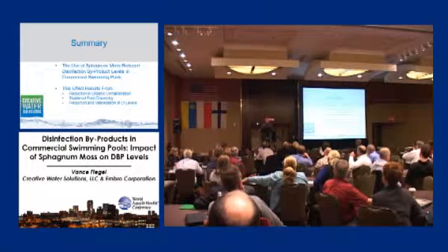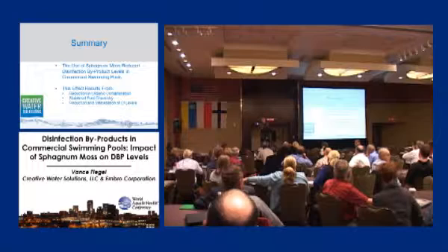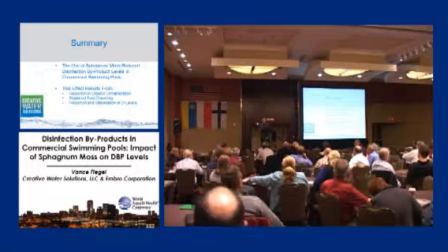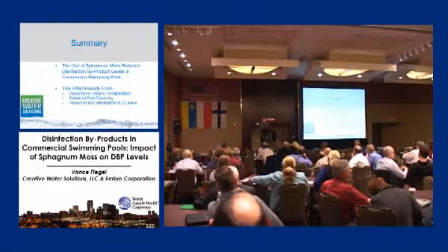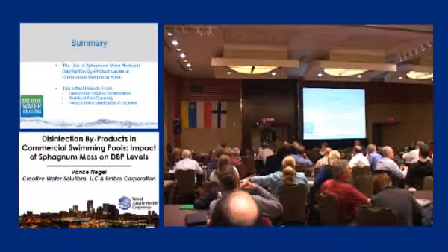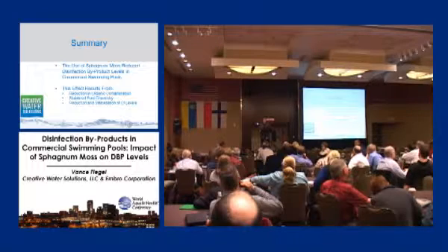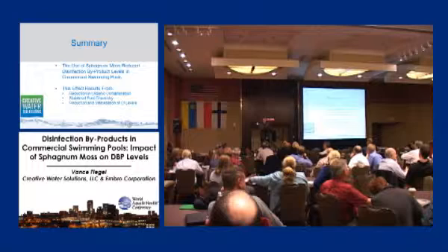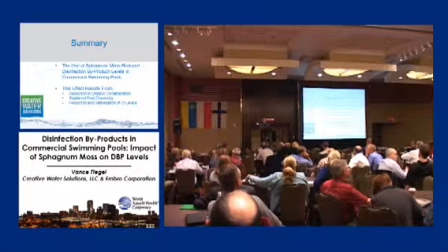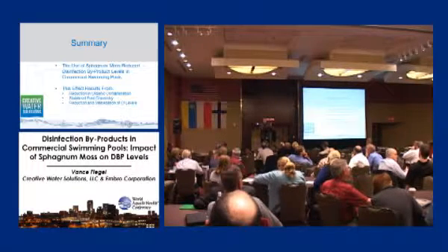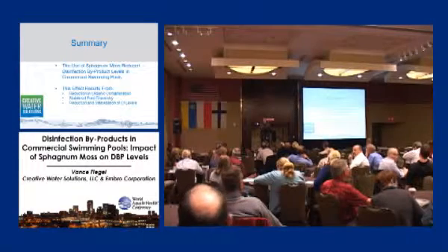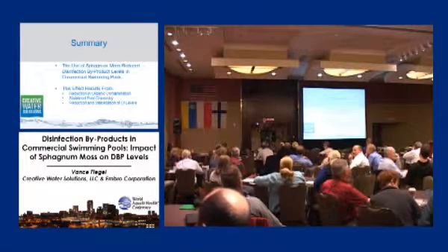We feel that right now the mechanism is, as I mentioned here, that we reduce the organic contamination, so there's less substrate for the chlorine to react upon. So we don't think we're actually absorbing the disinfection byproduct, the actual product. We feel we're inhibiting the creation of the disinfection byproducts because we reduce the chlorine demand, because we reduce the organic contamination. That's our working hypothesis at this time.